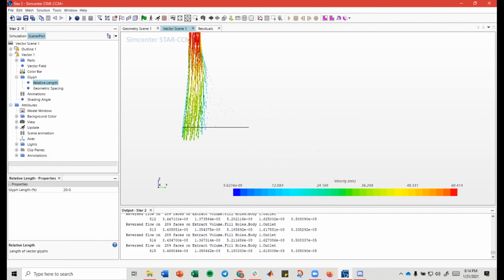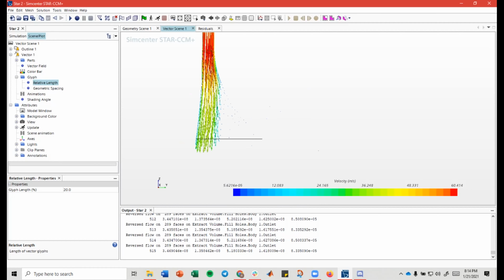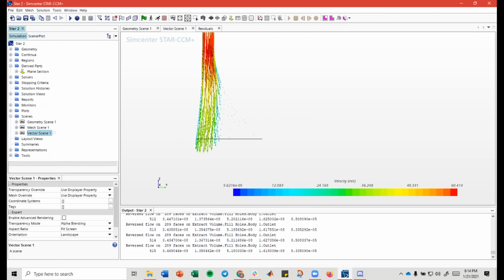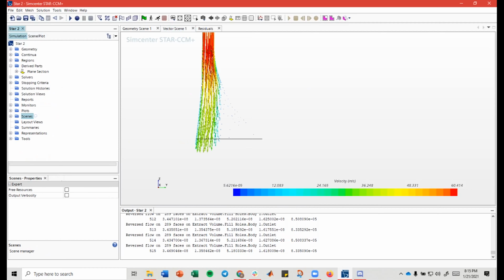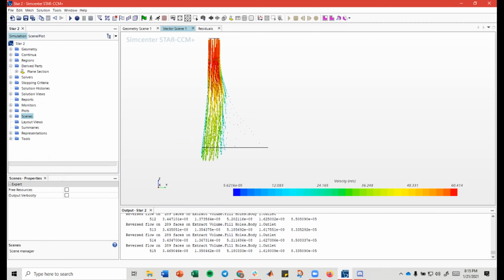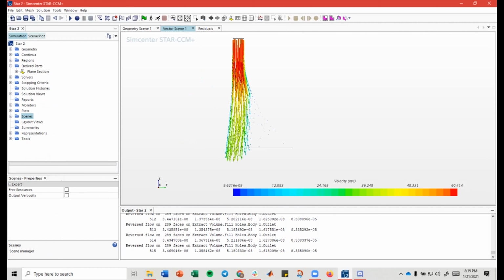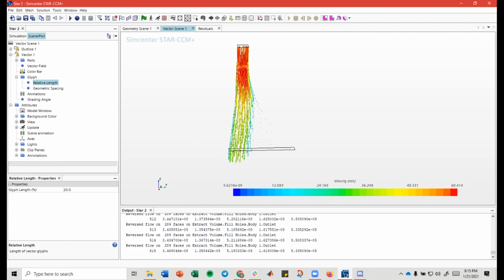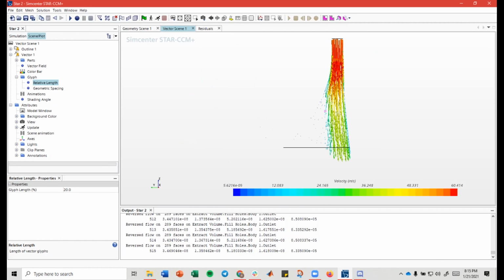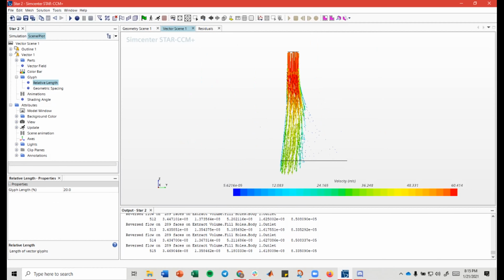One thing which I forgot to add before that we need to set up, let's do that right now. Oftentimes when we're running a simulation, we don't just want to see this and make a decision based off of this. Obviously, there's a lot more than just the visual aspect of the simulation. There are values that we want to gather. For example, we can gather the downforce that a wing produces. In this case, we want to measure mass flow through the outlet.